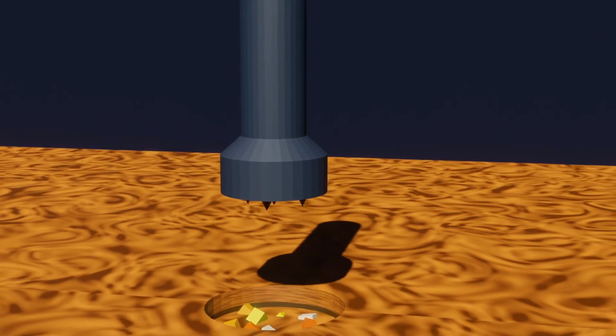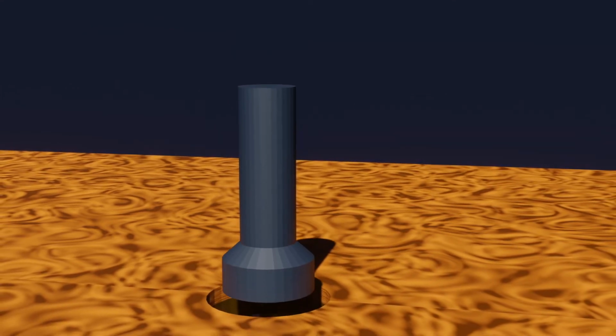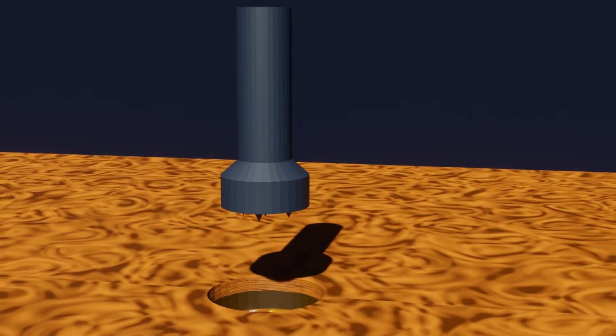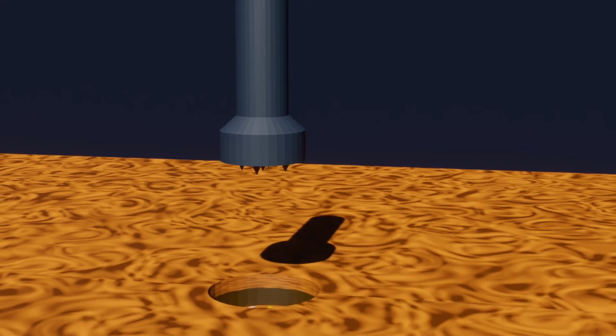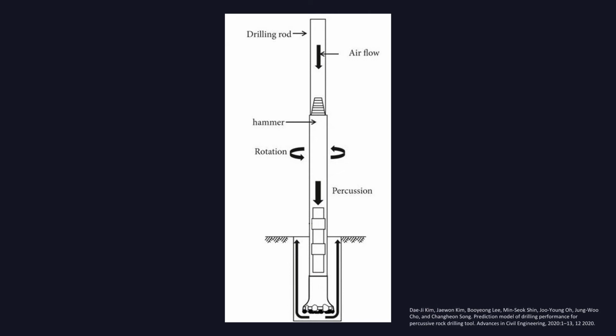Percussive drilling becomes energy inefficient for depths deeper than 10 meters because of dissipation effects in the drill column. Deeper levels may be reached by combining percussive elements with rotary drilling. To realize this, the rotary drills are modified by attaching downhole hammers.